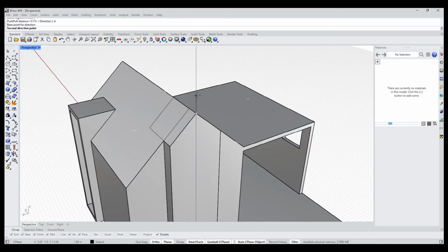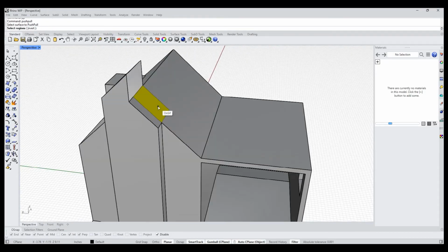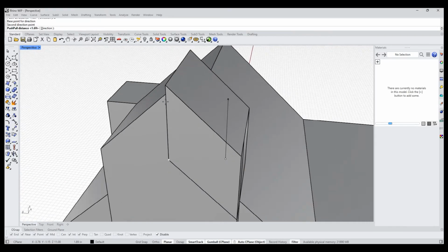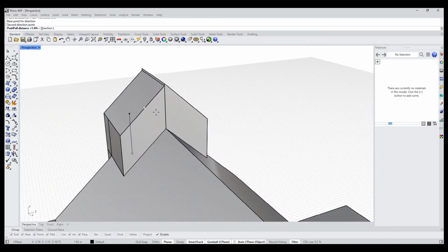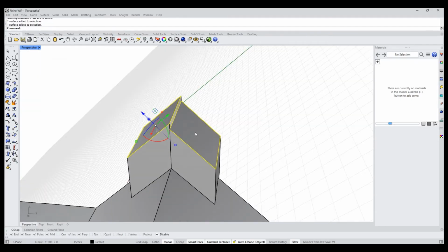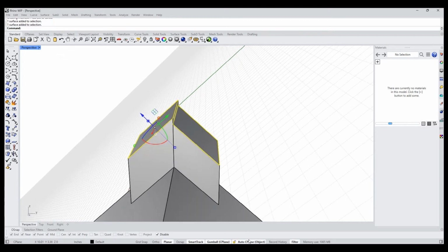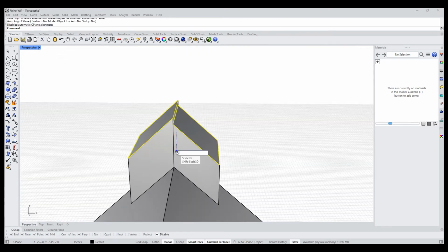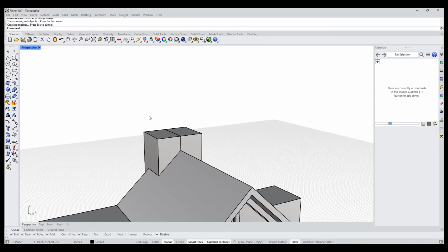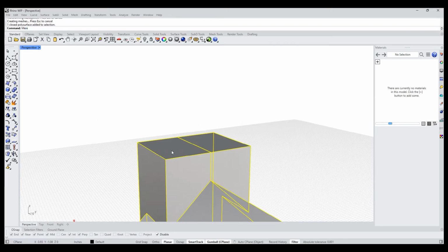And you'll notice in Rhino 8, see that blue line? That's a vertical snap. And I'm going to just pull this guy up like that. I'm going to do the same thing. Shift click to get that second piece. And let's bring this up. Doesn't really matter because we're going to take both of these and turn the auto CPlane off, and I'm going to scale to 0, and that's going to flatten that whole thing out. See that? And then we can merge.